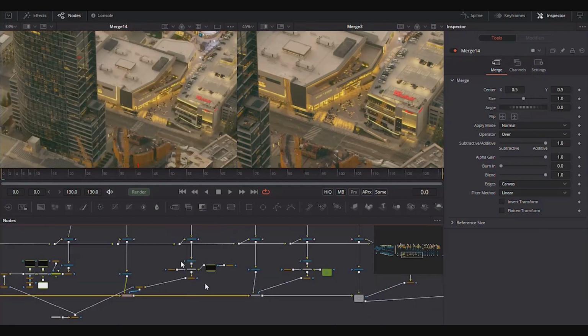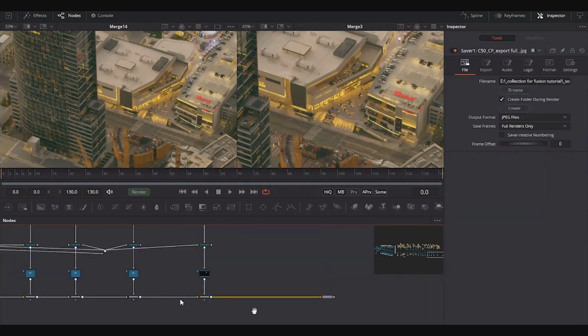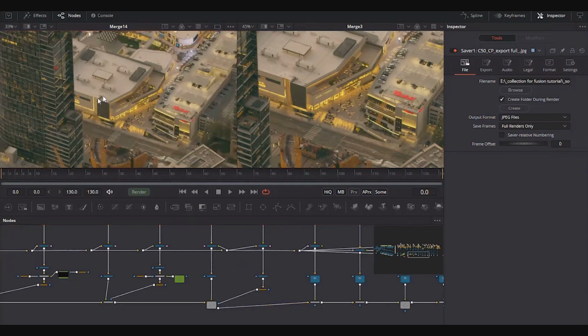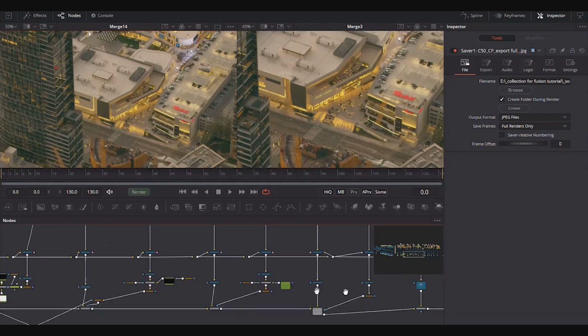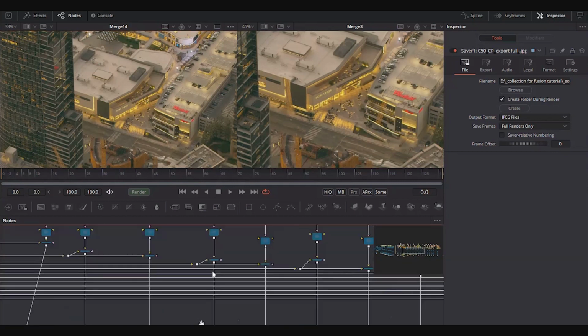One important thing to note about this as well is that after each section, which I didn't include in the earlier parts of the video, I plugged it into an output node and rendered the full sequence out. It's really important to do this to check it in motion. You can review your full sequence, you can zoom in on areas in DJV Viewer, you can make notes about what still needs cleaning up, and then the next time you get in the Fusion document, you can mostly work with a static single frame. So that's where we were.